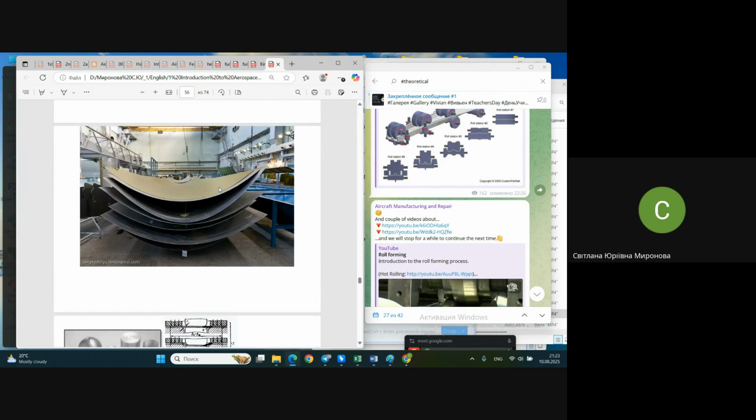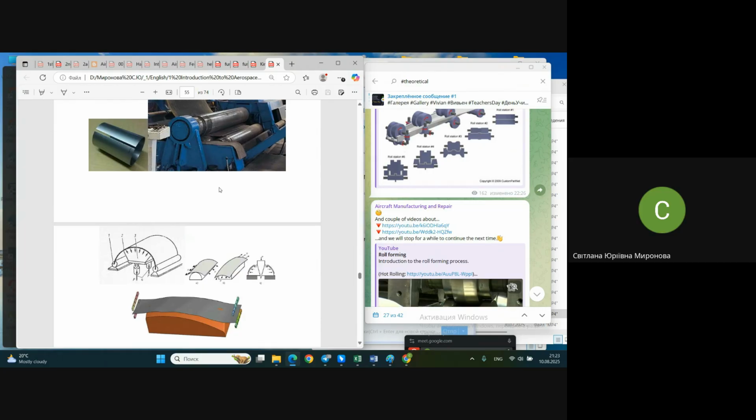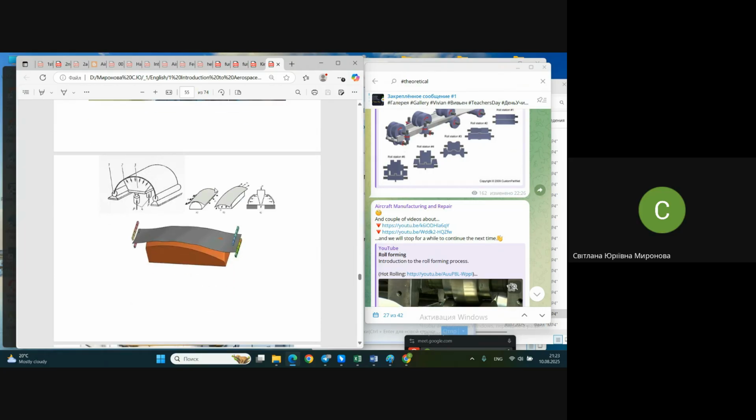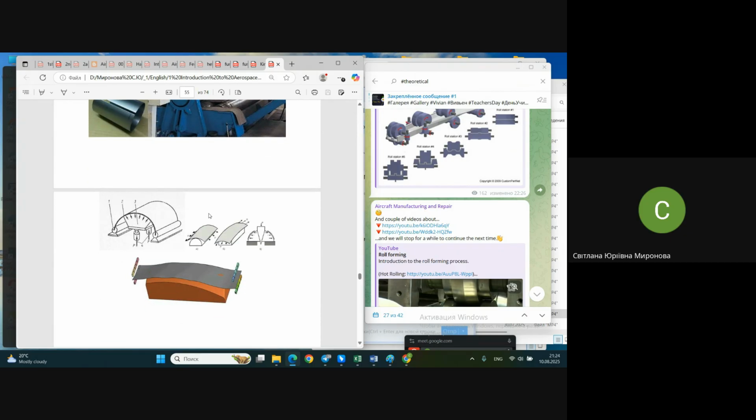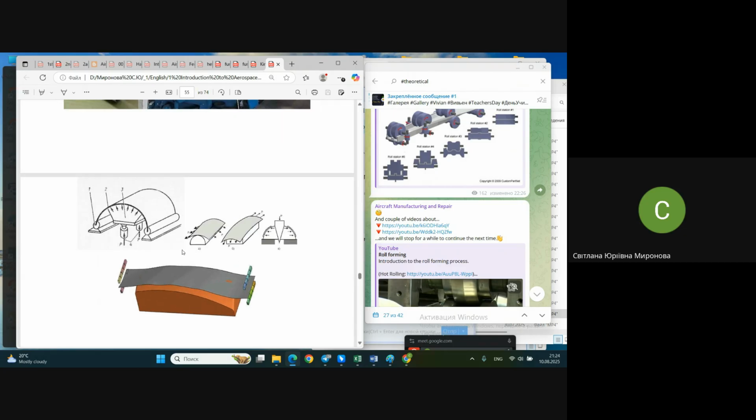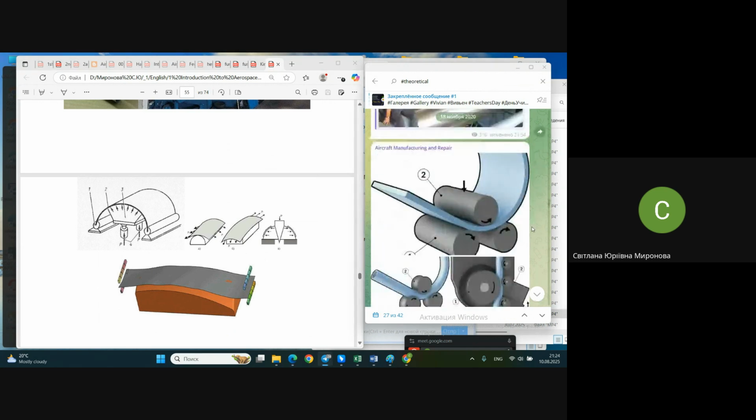And one more great way I will show you to save money is called stretch forming. Stretch forming, and when it comes to bending, it will be called stretch bending. The only difference is in the name: stretch forming for sheet, stretch bending for profile, but the principle is the same. What is this stretch forming about? You do remember I spoke about the spring back effect. Do imagine that you combine deformation, where it was the picture of spring back.